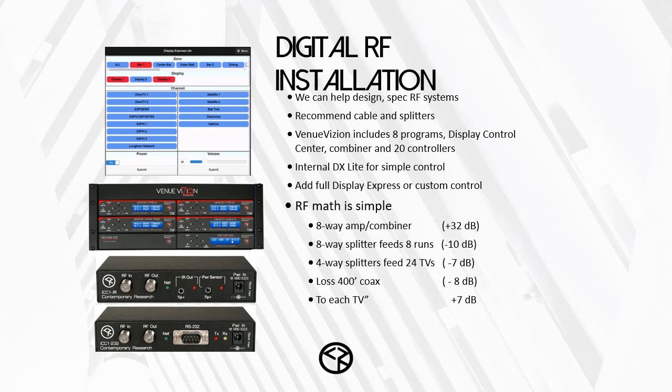And then that feed would go to an 8-way splitter, which will feed 8 separate runs to the TVs. Then you have 4-way splitters at the end of those runs, and each one of those feeds 4 TVs. So you're doing a total of 24 TVs. And let's say your worst case run is, say, 400 feet. Because we don't look at the total amount of coax that you're using in the entire system. All that matters in RF is, what's my worst case?